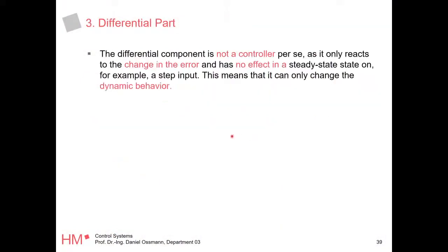Why is this pretty rare? Well, it's a differentiating element. Think of what a pure differentiating element would do. You put in a constant, and this constant is differentiated, it automatically gets zero. So this differentiating controller is not doing anything, it's just changing the dynamics, because when you have something constant as input, it will lead to no output. So it's only changing when you change the input variable. So it's kind of not really fair to talk about the controller here. Because it has actually no effect in steady state, right?